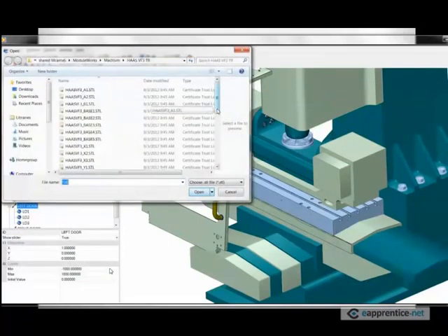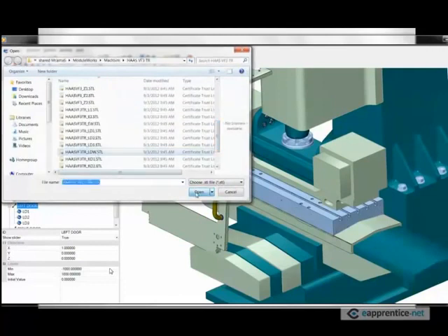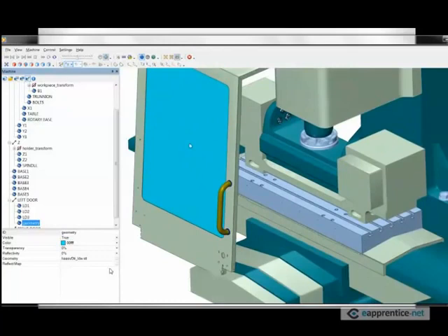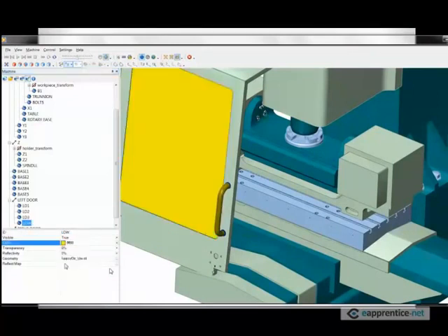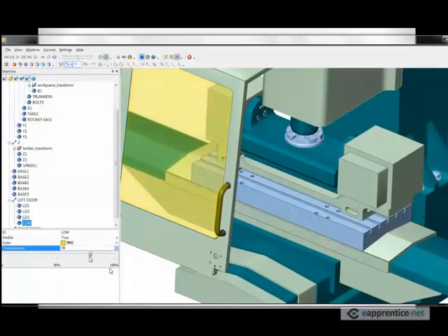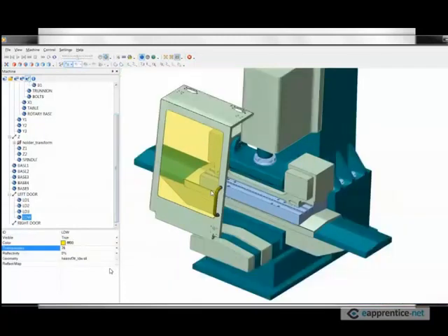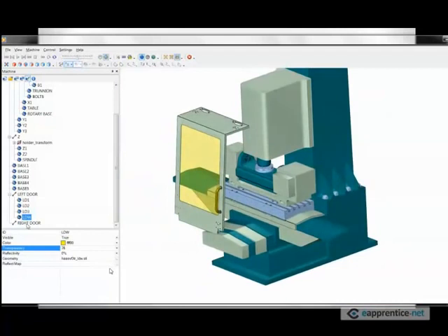For example, we are adding a window into this door, LDW, and we want to see through that window, so we're going to call it LDW, set the color. We want a yellow tinted window, and set the transparency to whatever you prefer. So by moving this scale, we can set the transparency to whatever that we can see through that window. And we will do the same thing on the right window. Again, this is a repetitive kind of work.